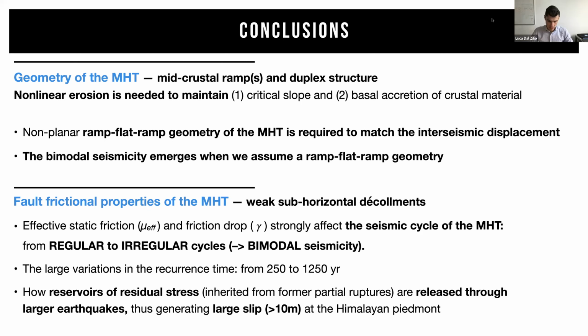This is a very important point, because when we try to dynamically change that, we have to consider different criteria. Otherwise, the code will become unstable. We can clearly see that because we have internal iterations, what we call global iterations, where the code should converge. And if the time step does not become small enough, it will start to iterate longer and longer. So we have different criteria.